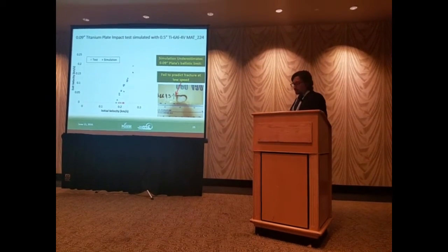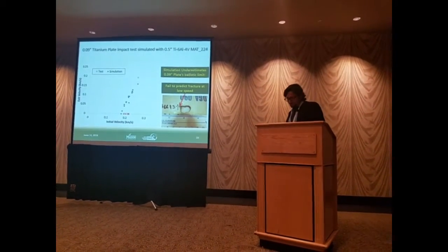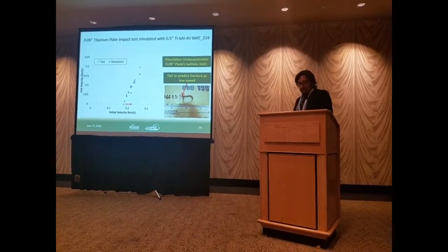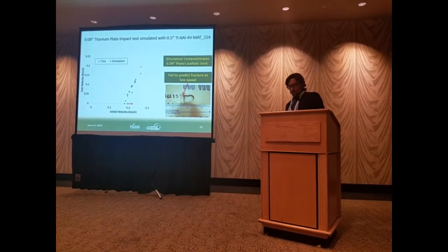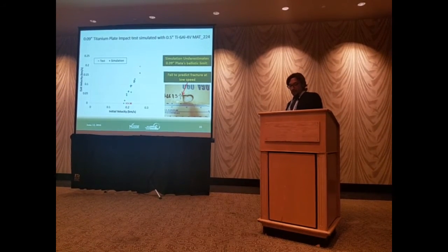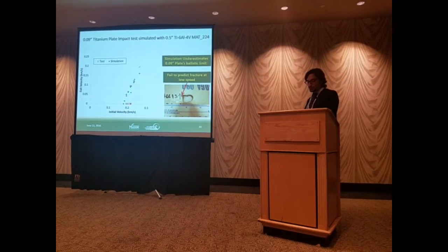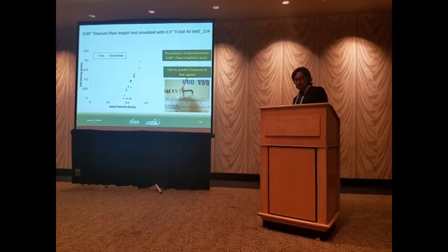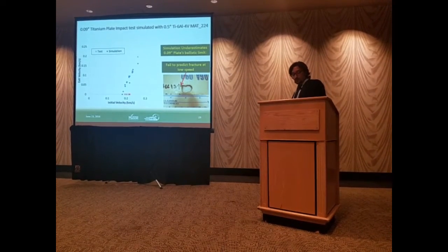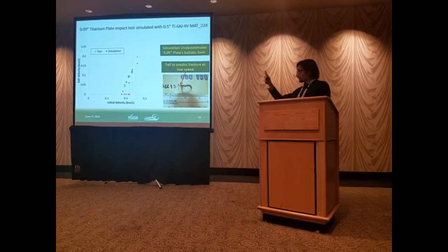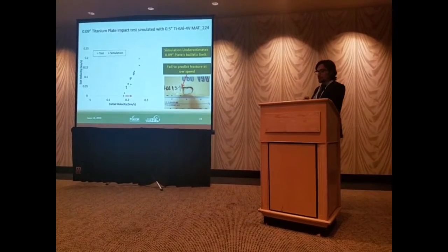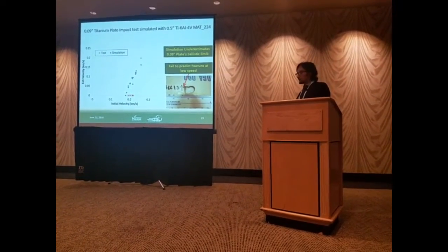In the figure on the right, you can see a fracture failure mode, and when fracture occurs, there is more material involved in the failure, which means that more energy is absorbed by the plate. And our simulation doesn't predict the fracture very well, and for this reason, the ballistic limit is lower in our simulation. Furthermore, the experimental curve just for the 0.09-inch plate doesn't follow the trend that we are expecting from the analytical formula.